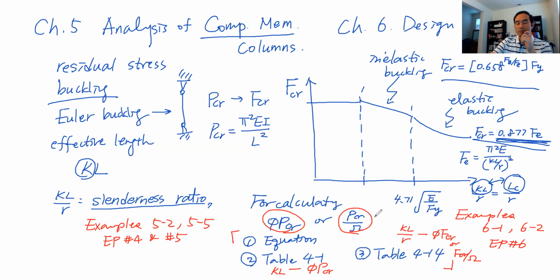So we covered example problems like this. If we know that the weak axis of the column will be the governing axis, based on the boundary conditions, and we have effective length given, then you can always go to table 4-1, because table 4-1 is constructed based on the KL value with respect to the weak axis, y axis.